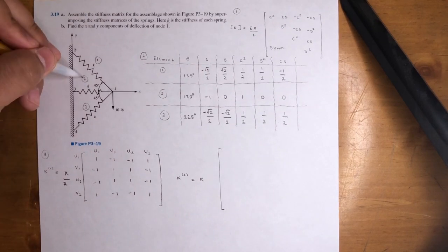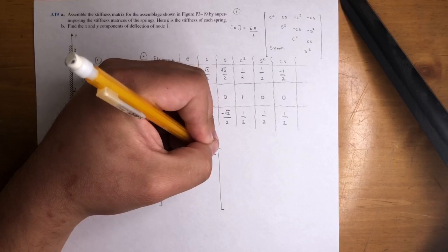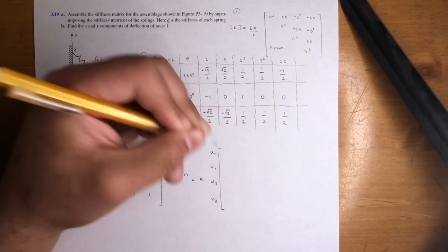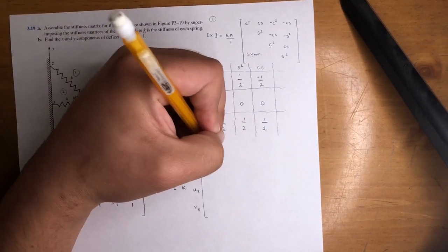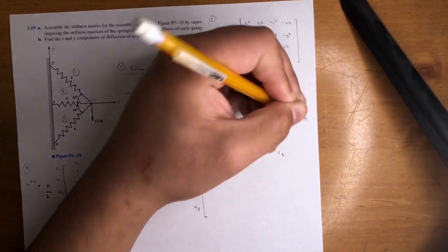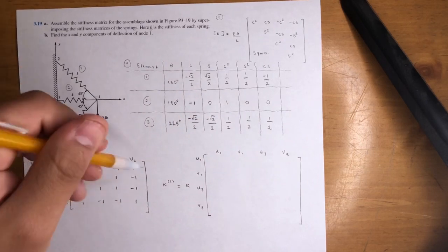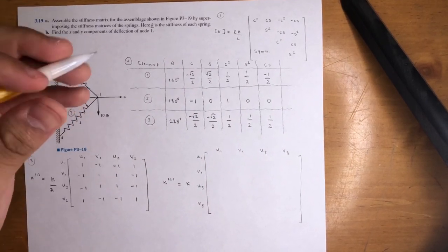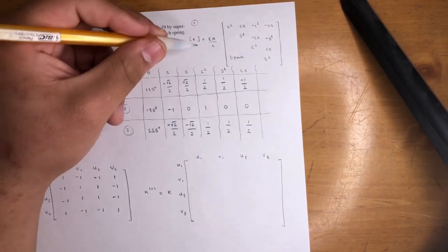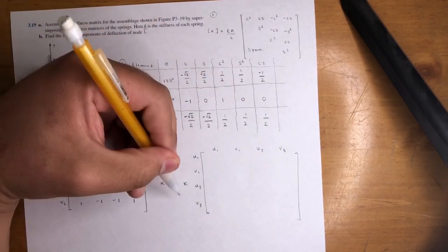Now it's the second element, right? K2. It's between nodes 1 and 3. So you've got U1, V1, U3, V3. Then same thing up top, U1, V1, U3, V3. You want to be neat, okay? I'm going a little fast here, so it's not too neat, but just make sure you don't get lost. We've got U1 now. Normally, I factored out the half here, right? But these are just perfect 1s and 0s, so I'm not going to factor anything out.